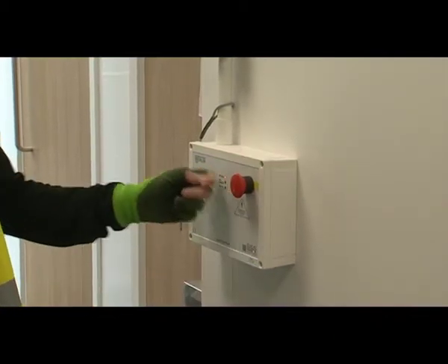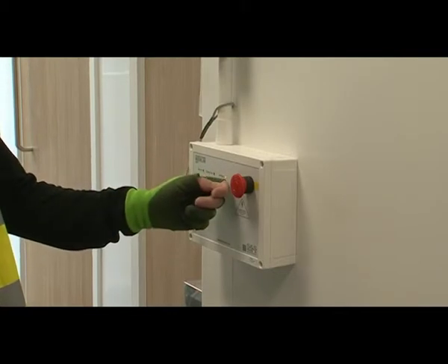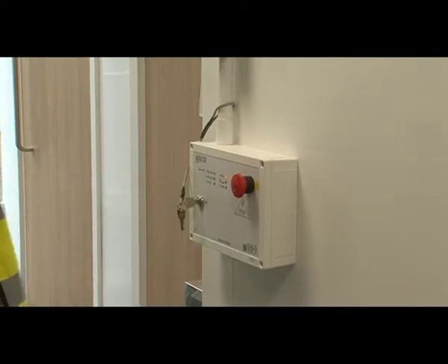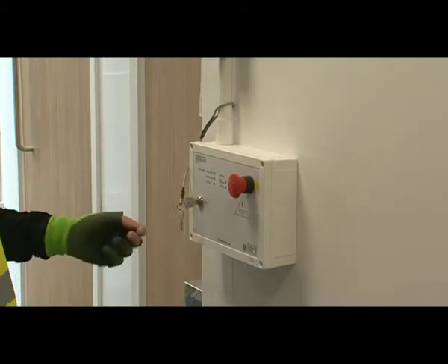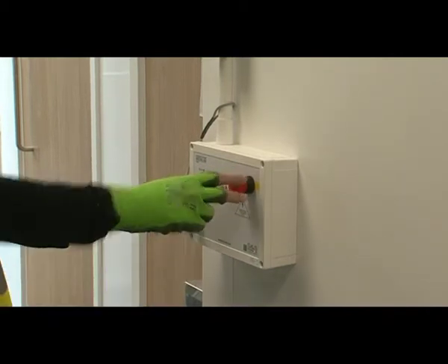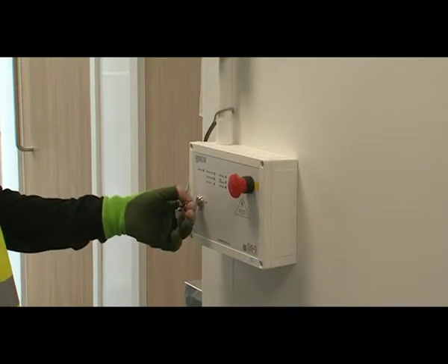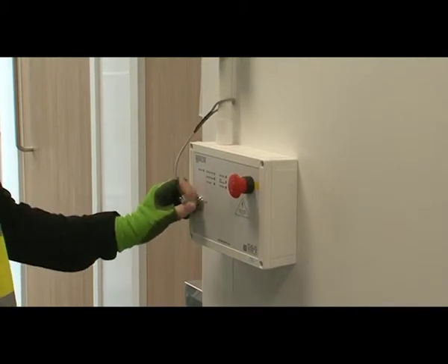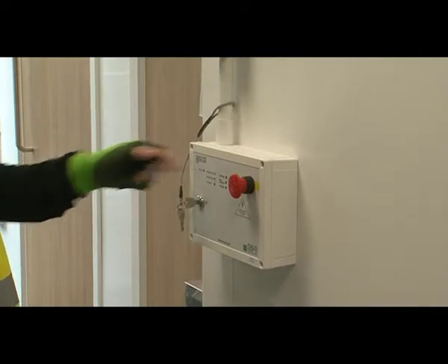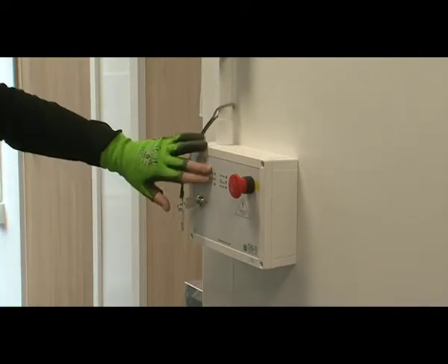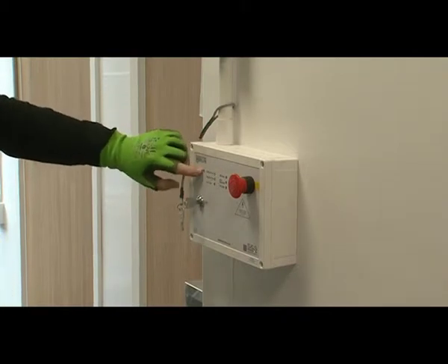That will shut the gas off and give an emergency stop status and the audible alarm. That's reset by twisting the knob in the clockwise direction, which releases the emergency stop. Switching off and switching back on will reset the unit, and then it'll carry out its checks on the fans. If the fans are running, like I said, these go solid green and will give gas.